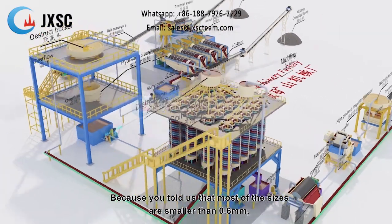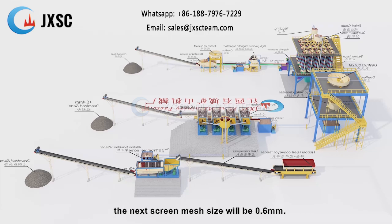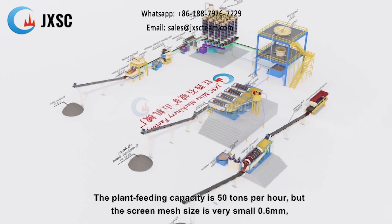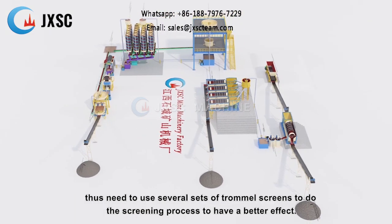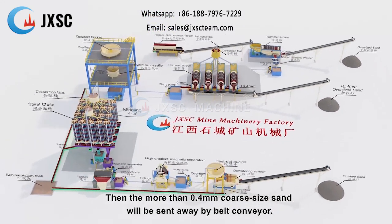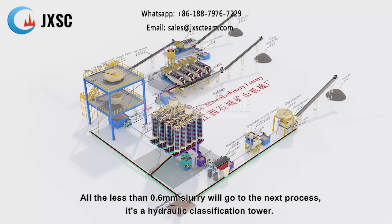Because you told us that most of the sizes are smaller than 0.6 millimeters, the next screen mesh size will be 0.6 millimeters. The plant feeding capacity is 50 tons per hour, but the screen mesh size is very small, 0.6 millimeters, thus we need to use several sets of trommel screens to do the screening process to have a better effect. Then the more than 0.6 millimeter coarse size sand will be sent away by belt conveyor. All the less than 0.6 millimeter slurry will go to the next process.